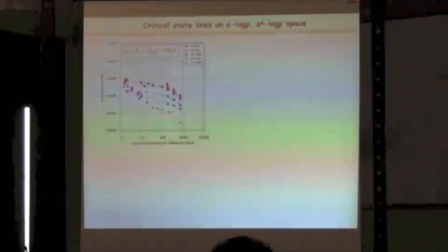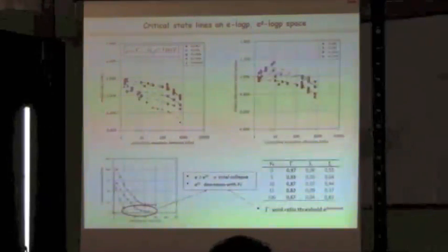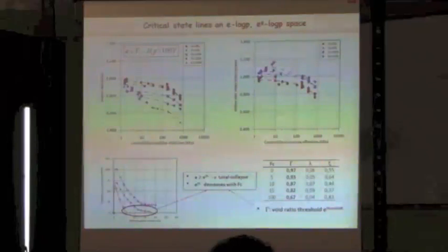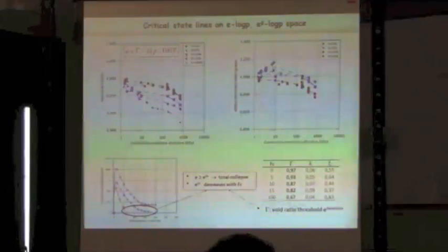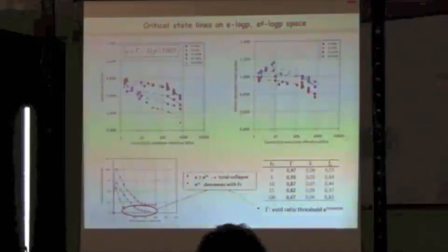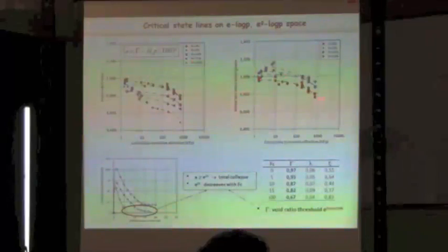Okay? So now when we present this critical state in terms of intergrain void ratio, we have an inverted tendency. In this case, the shear resistance increases with the fine content, and also it is consistent because the sand skeleton here is constant, and we just add some amount of fines.